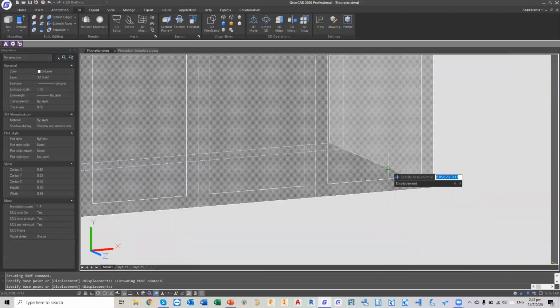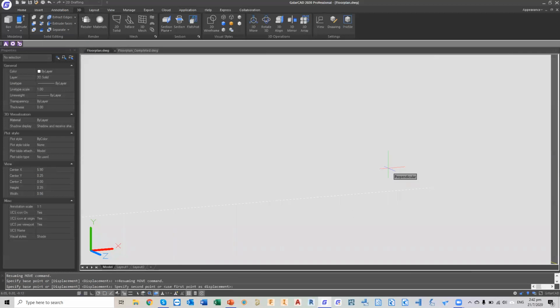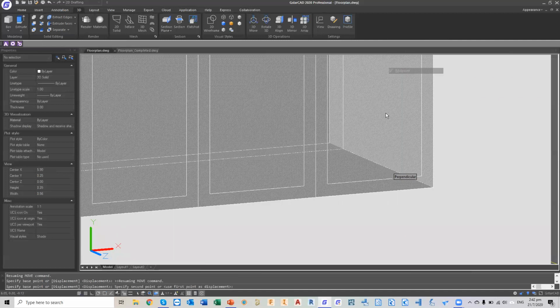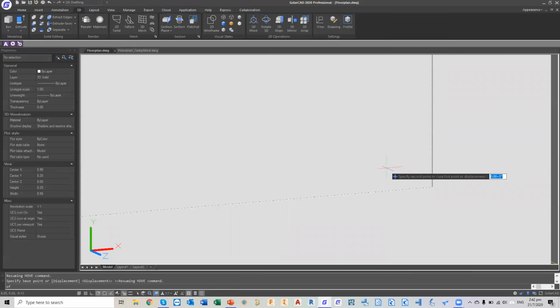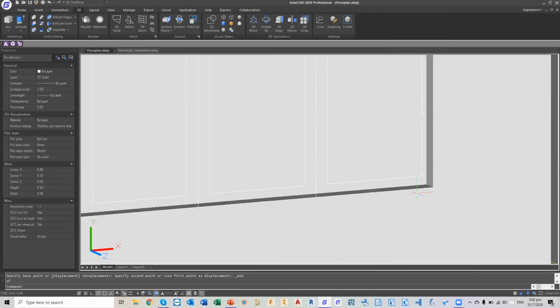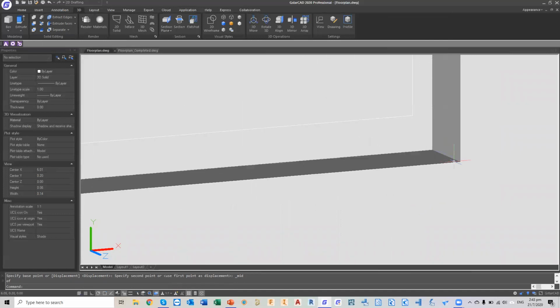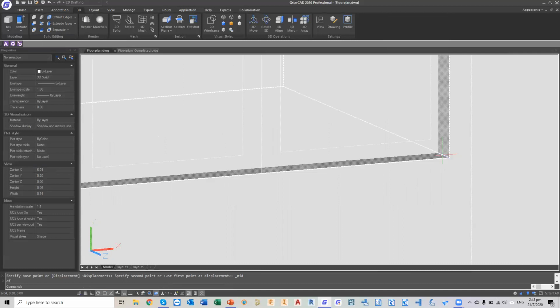So you can see I'm able to snap to the solid center point here. Click, and then I will do a snap override, and then go to midpoint, and then I'll move my solid here, and then snap to the midpoint. Right. So you can see there's actually a gap of 0.2 meter away from the solid over here.